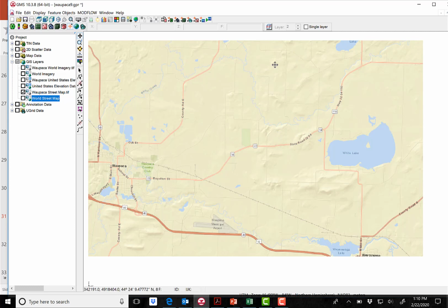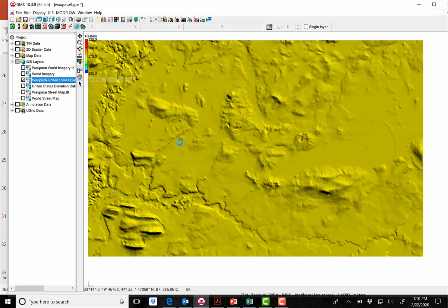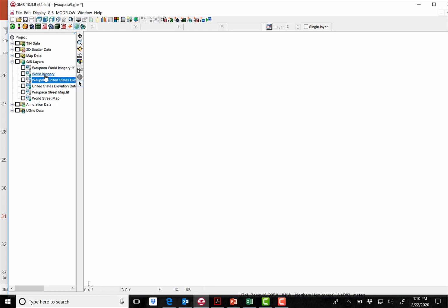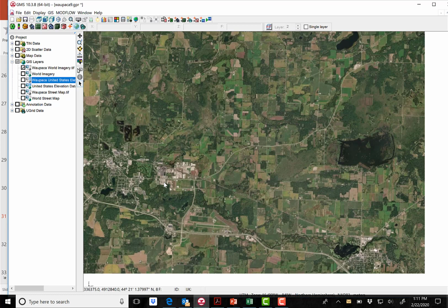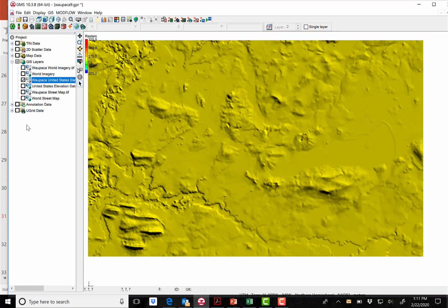Once I identified this frame, I did the same thing for the elevation data. I downloaded the elevation data from online maps, copied it, and made this file that is the elevation data. And I did the same thing with the air photo. I used online maps to bring in world imagery, and then I copied it to this file. So I have all of these 3 different kinds of images that I can use, as well as the data in this file that I can use to generate other files. So you can see here the stream valleys, and then these linear ridges in this glacial terrain.